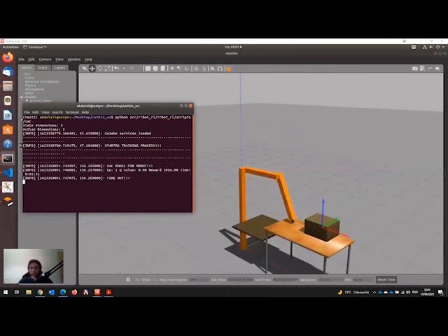So I was saying that we give a 1 second delay, not for the training but for the simulation, because otherwise the simulation will run so fast that it will throw the box when touching it, because the velocity is higher, and that's how physics works. To avoid that problem, I made sure there was a 1 second delay.